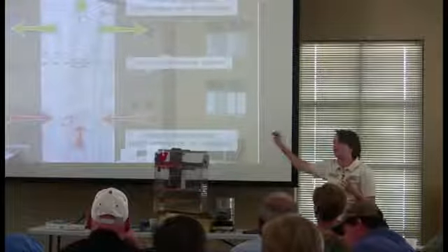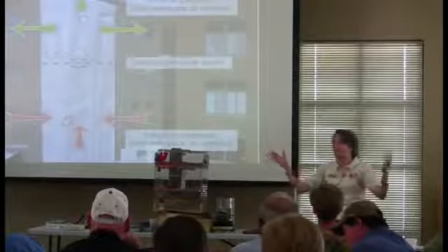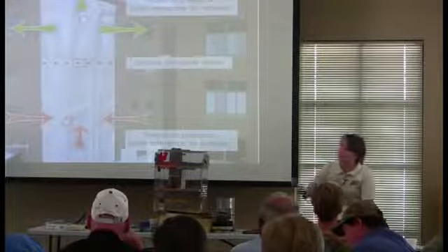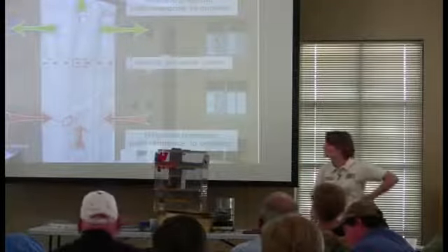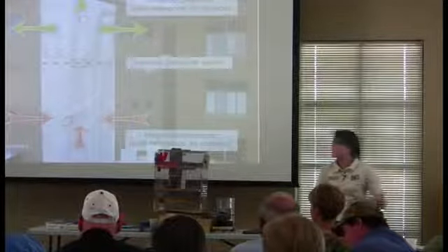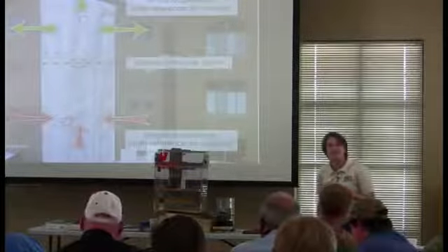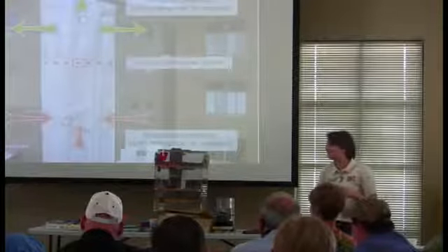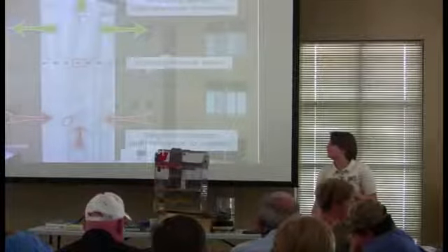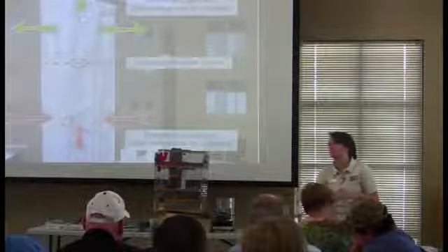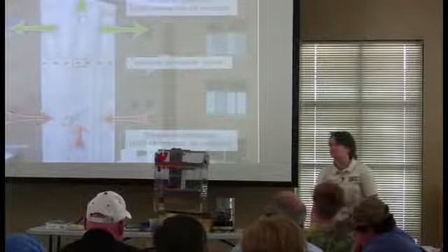If we had a hole in the red or the black dotted line, isn't that amazing? If you had a hole right there at that dotted line, no air's moving. You could have the biggest hole you could drive a car through, and because there's no pressure difference, there's no air movement. I usually like to smell a magic marker and think about this. But anyway, do you get the idea that the stack effect is always causing pressure differences inside and outside of a house? But it's not that strong of a force. It's pretty weak. It's a function of how tall your house is and what the temperature difference is. So you get more stack effect in the winter than in the summer.